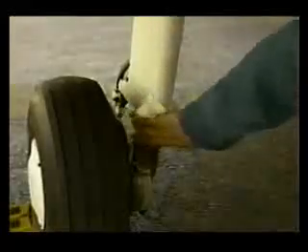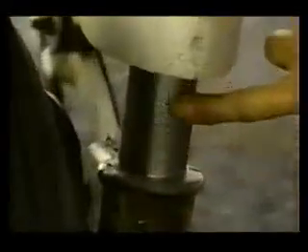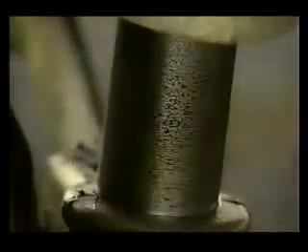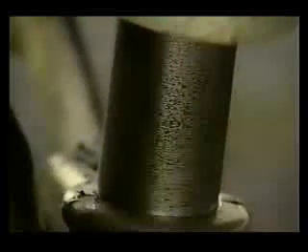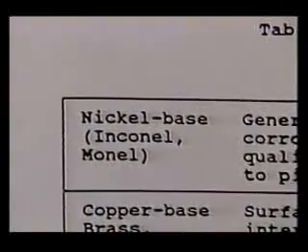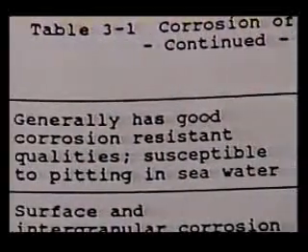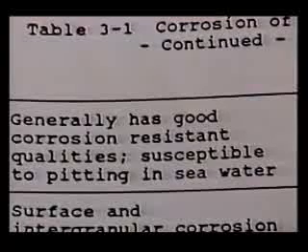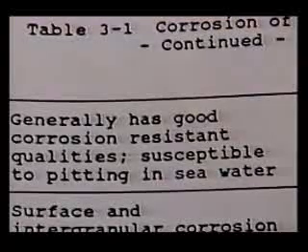Chromium is a protective coating which provides a smooth, wear-resistant surface that can be polished to a high luster. Chromium's continuous oxide coating protects not only itself, but the underlying metal as well. Even though very smooth, the surfaces of chromium coatings contain tiny cracks, which encourage pitting and will promote rusting of the steel underneath. Nickel plating is used for corrosion resistance, typically in a saltwater environment, and like chromium, the thickness of the coating determines the amount of protection which is given to the metal underneath.